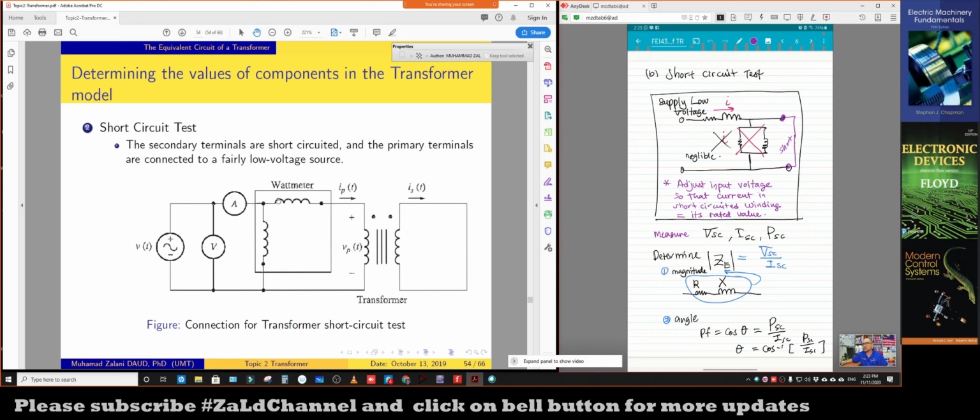So from that, we can measure voltage at the short circuit, current at the short circuit and also power during the short circuit test. Once we get all of these values, VSC, ISC and PSC, we can use these values from the experiment to calculate ZE.